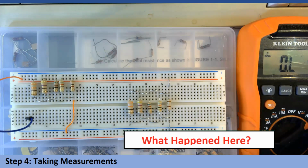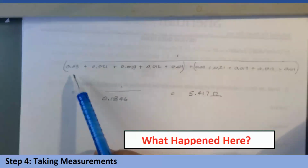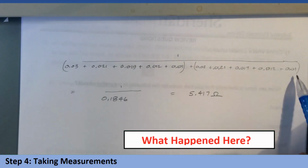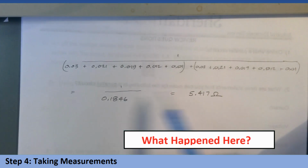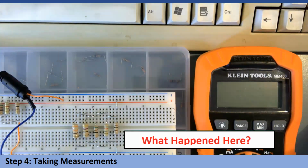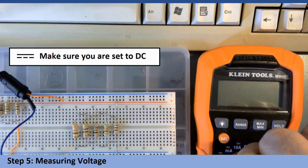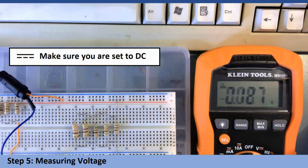Let's check the math on that. Okay, so if I take my reciprocals and I add them up and then add them again, I come up with 1 over 0.1846. When I divide that into 1, I come up with 5.417 ohms, which is really close to what I was reading. Now, we're going to do a series of voltage readings to see what the voltage drop is across each resistor. So I'm going to turn my meter on to volts. I have it on volts. I'm going to take my first reading, watching polarity.